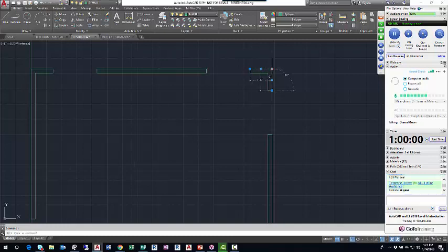One is at a 0 degree angle, one is at a 90 degree angle. So when you have line work, you can very easily use your dynamic input to show you how long something is if you select it and hover over the end grip. But if you've got an opening, there's nothing here I can select to let me see how big this opening is. So I'm going to use that distance tool. And this time I'll open up the whole suite.